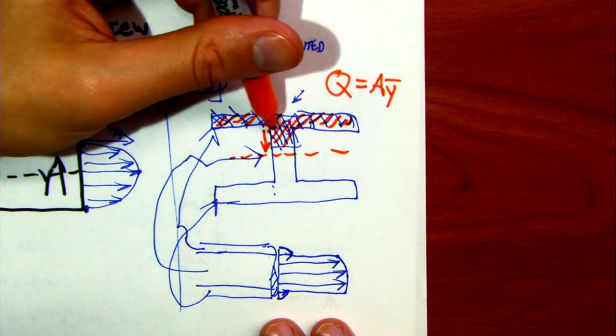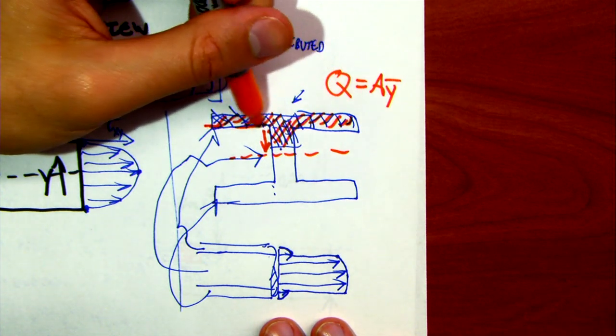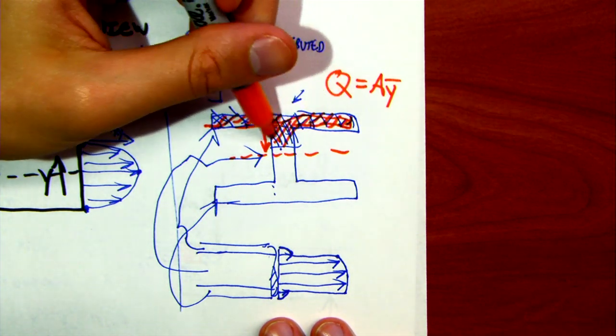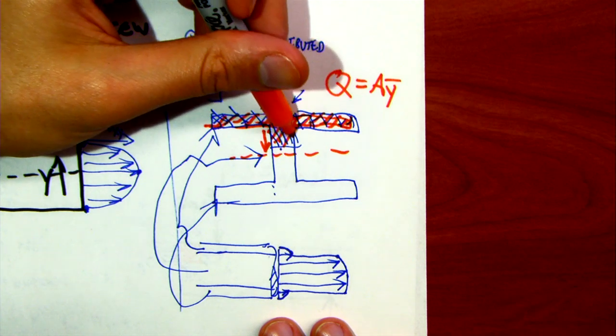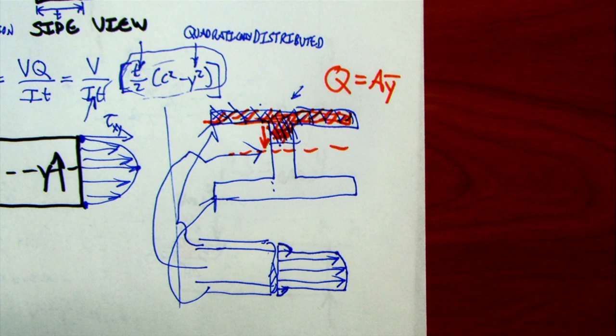But we're going to have to solve for at least 2 different cases here. The case where we just have this top rectangle, which is relatively straightforward, and the case where we have the top rectangle and some of this middle section, the shear web, as it's called. I-beams are made out of 2 parts.